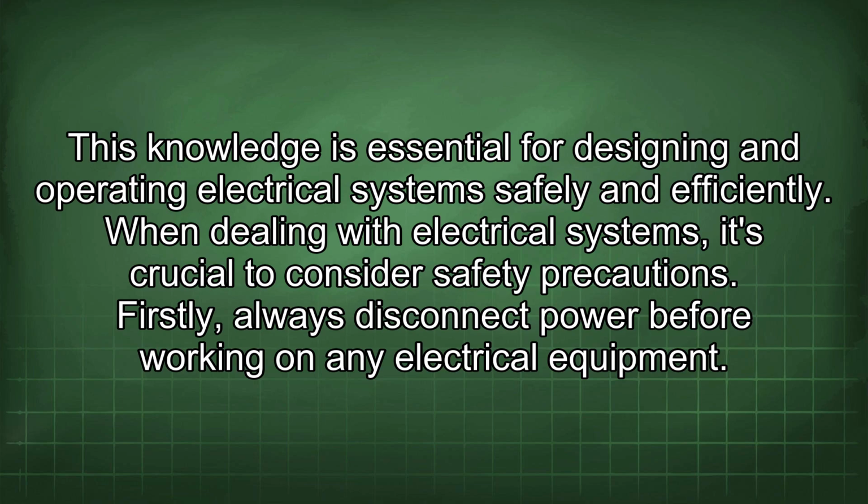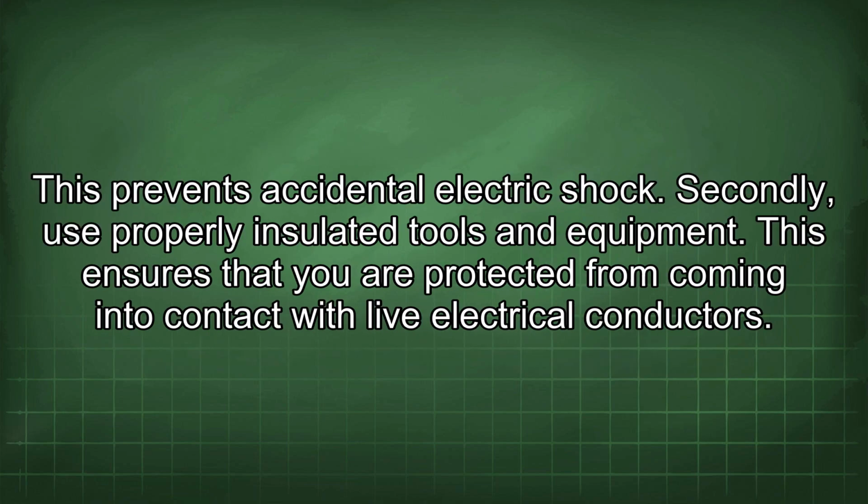When dealing with electrical systems, it's crucial to consider safety precautions. Firstly, always disconnect power before working on any electrical equipment. This prevents accidental electric shock. Secondly, use properly insulated tools and equipment. This ensures that you are protected from coming into contact with live electrical conductors.